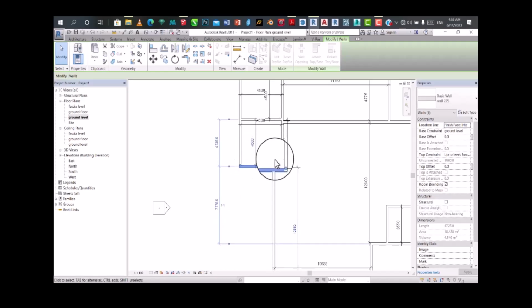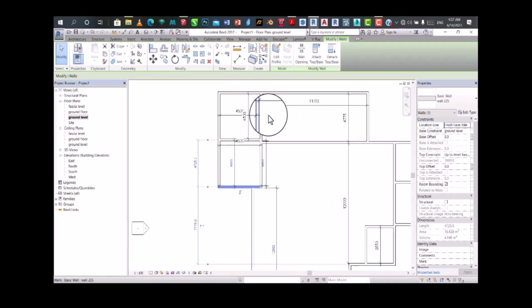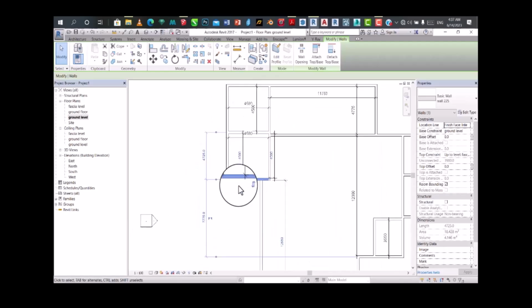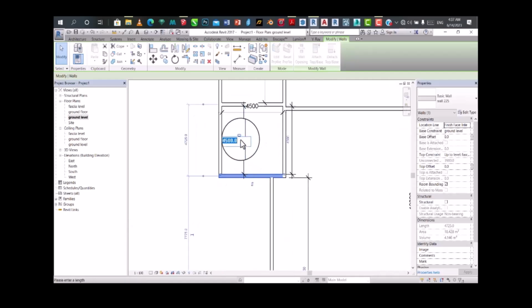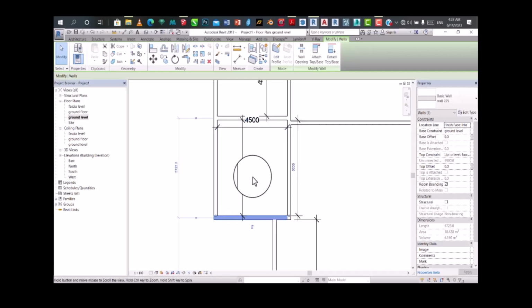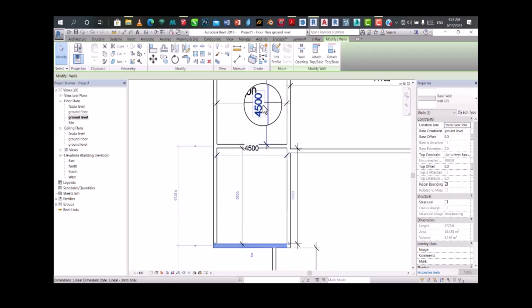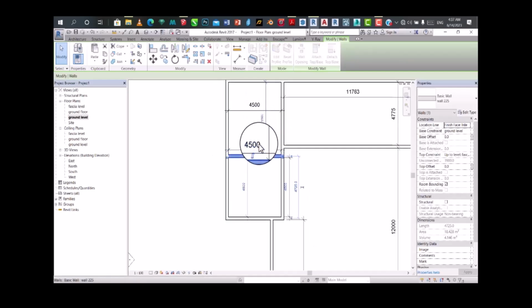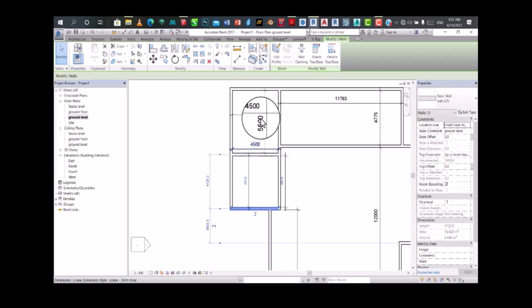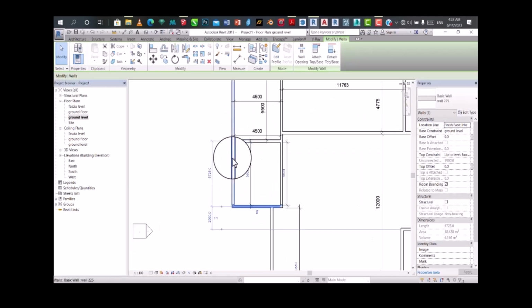Okay, we're done with our rooms. Sorry, let's make it 5.5 so that we can have our ensuite toilet inside our restroom. Okay, let's make this one 4.5 actually. Automatically this one has already changed. Once you click a wall, it alters the dimension. You can actually take this one and make it 5.5. So now everything is 5.5. So we can actually have our restroom here.